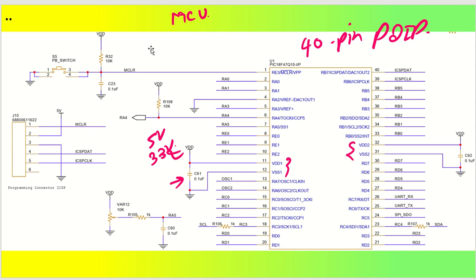and actually it is recommended that you give one series resistor as well. So a series resistor you have to connect here, let's say 470 ohm or less. Okay, so I will start with 470 ohm. So please make a change of a 470 ohm series resistor to this particular line. Got it?